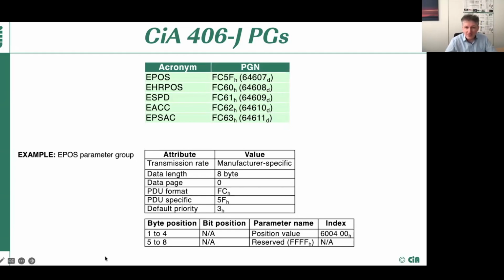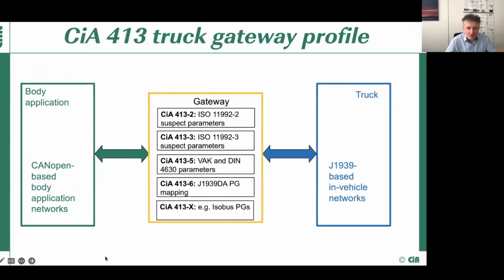For the moment, in this case, you don't need an object dictionary or service communication yet; it could work by itself. Since the position value parameter is only 32-bit, we still have some space reserved. We reserved it for an important reason, so that manufacturers do not put something else there. Thus it would be completely identical to the corresponding PDO in the case of a CANopen encoder with this position value.